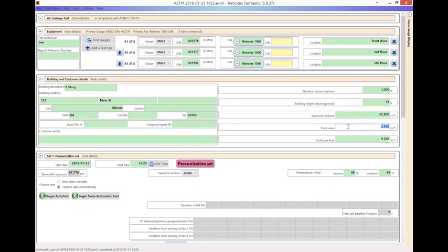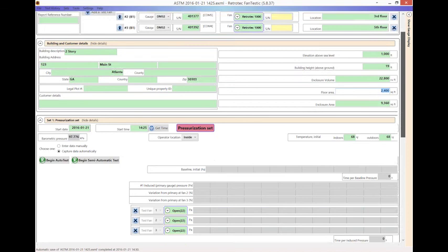So the floor area is, as you may think of it for a duct test, a 2 floor, so each floor is 1,200. The enclosure area is all of the surface area from all of the sides that are exposed from unconditioned to conditioned area. So all 6 sides, the floor, the ceiling that goes to the attic, that's my total enclosure area. And my volume is the same thing many people are used to using when they deal with air changes per hour. All right, we'll scroll down.